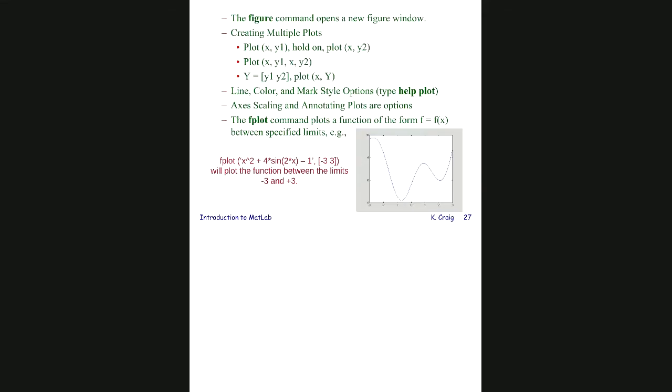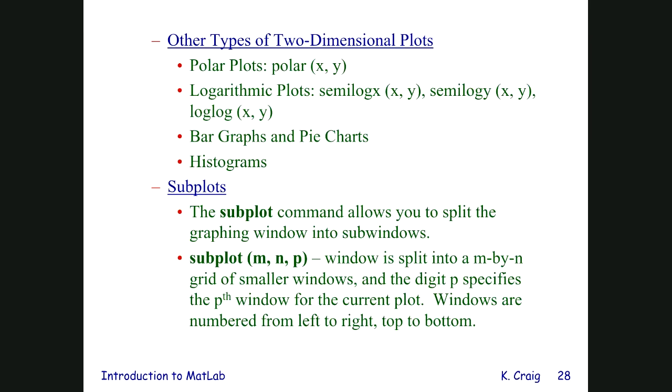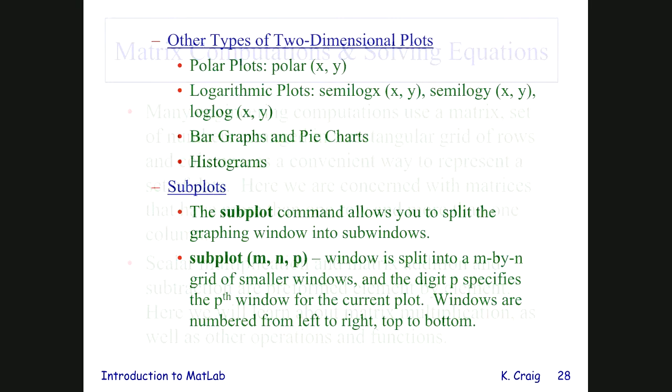So I can put multiple plots, like two things together plotted with respect to y. I can use fplot, for example, which plots functions directly. By the way, MATLAB is enormously big. You cannot imagine how big it has become. You can have logarithmic plots, bar plots, histograms, etc. Subplots let you have two plots in the same chart, in the same picture.